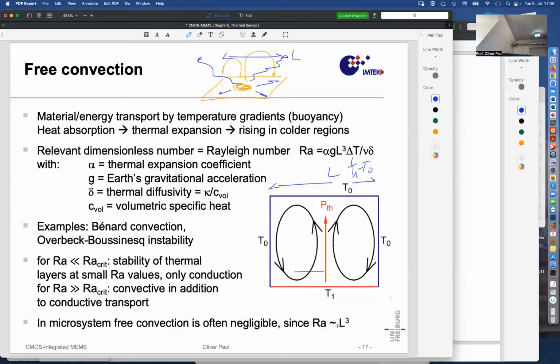And then let's turn it over. Once the hotter surface is below the cooler environment, whereas here the hotter is above the cooler environment, definitely the dynamics will be different. Hot air may want to rise, but where it's already hot is on top. And we didn't see any difference at all as a function of time. So we experimentally concluded that free convection was not important in these sensors.